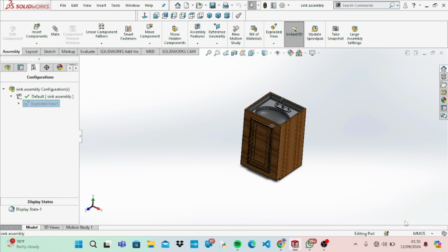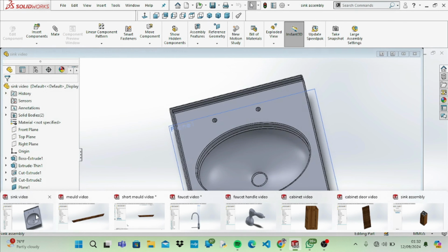They can also display movement between related parts within their degrees of freedom. The components in an assembly are defined in relation to each other using assembly mates. You can attach assembly components using various types of mates such as coincident mates, concentric mates, and distance mates. So without further ado, let us start the assembly of these components.